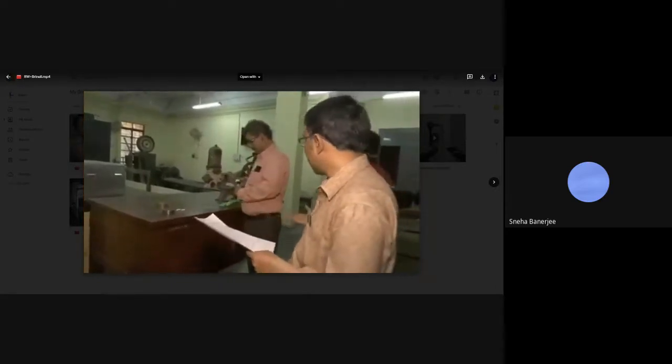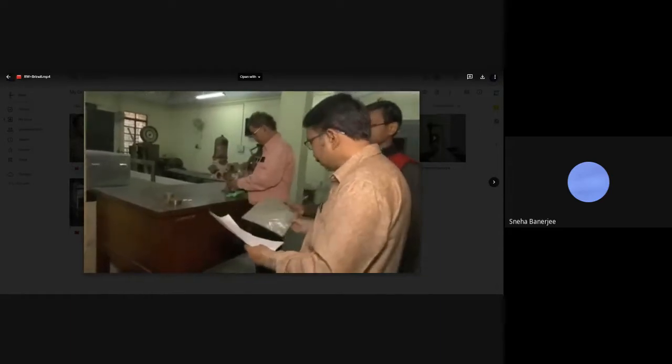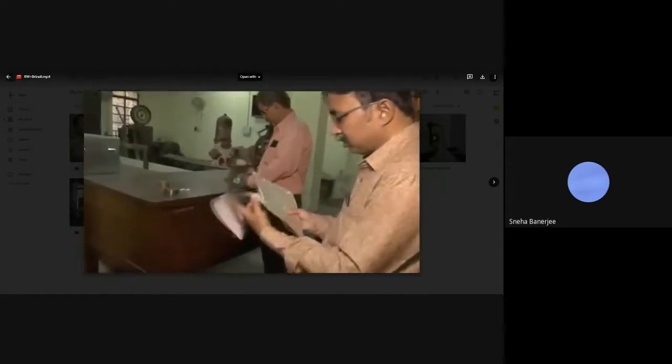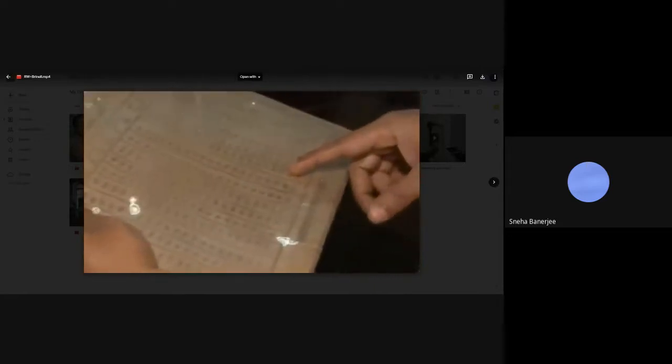Now we can see the chart. See the chart with 3000 kg load and 5.8. Where is the value? 5.8 here. 5.8 means how much? 103. 5.8 means 103. So the Brinell hardness number is 103 for brass.